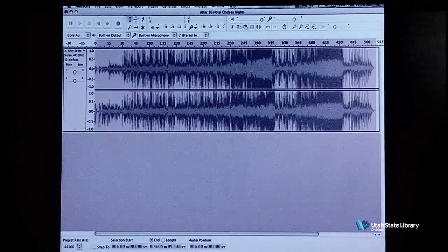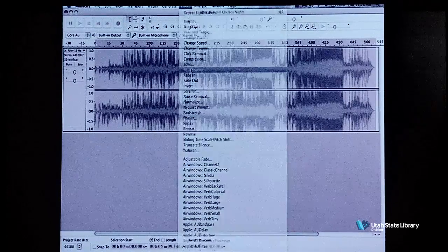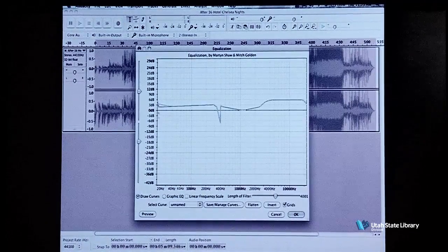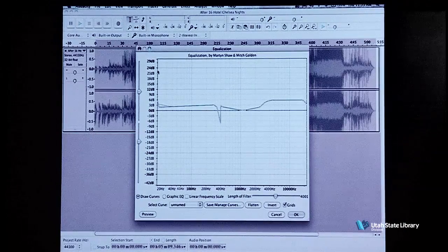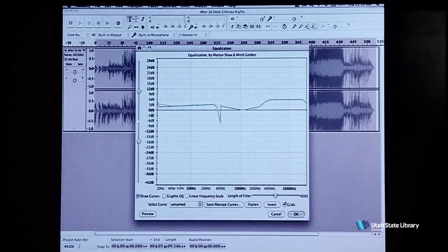Yeah, essentially, if we're dealing with an axis of an equalization, the sidebar here is all the decibel volume. So that's how loud or how quiet you're taking it. At 0 dB, that's essentially the zeroed out point. You're not doing anything to it if it's at 0 dB. If you're boosting it, it's going to be into the plus. If you're taking it down below that line, like this point right there, you're basically turning down that specific frequency for that specific point. Okay, make sense? Yeah.